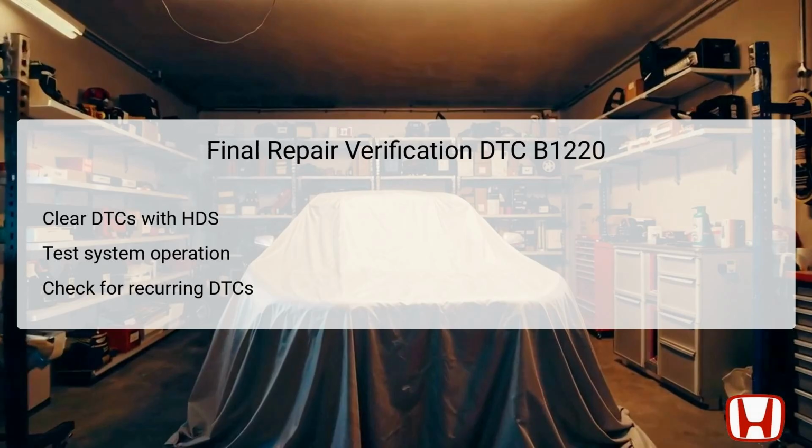After completing the necessary repairs associated with DTC B1220, the crucial final step is to verify that everything has been resolved properly. Begin by clearing all DTCs using the Honda Diagnostic System, HDS, which effectively resets the onboard computer and allows for fresh monitoring. Following this, it is paramount to test the overall operation of the climate control system to ensure that the recirculation function is working correctly.